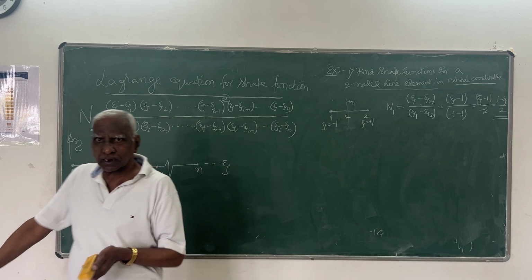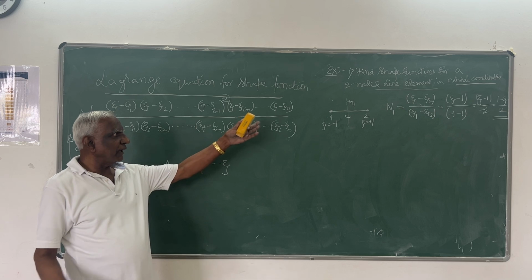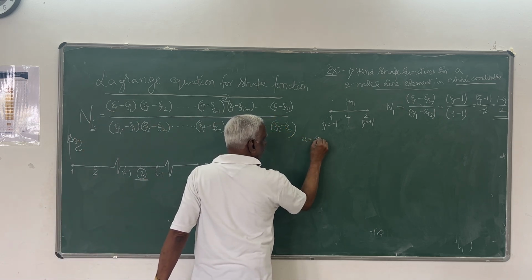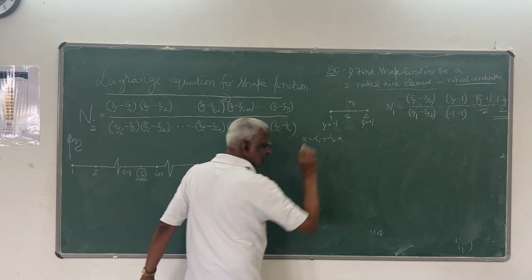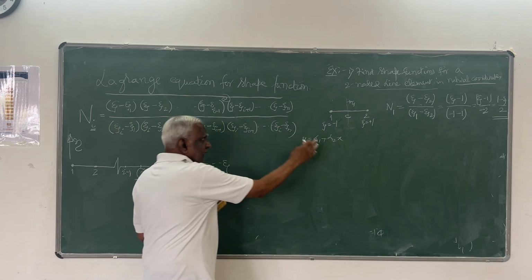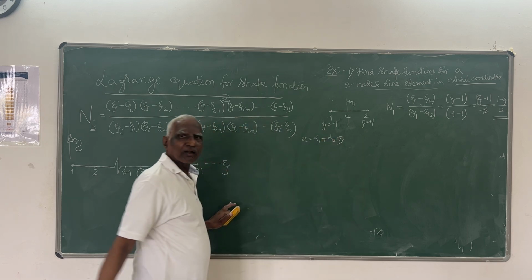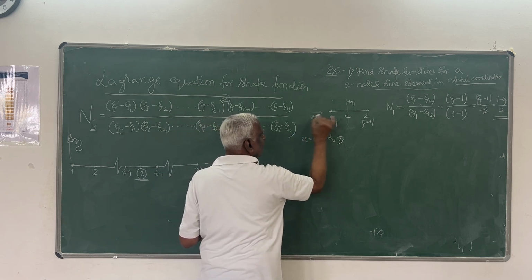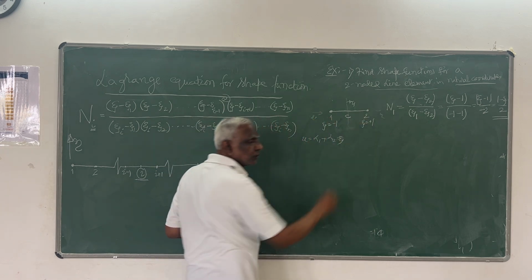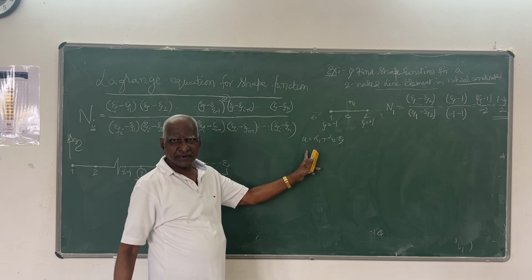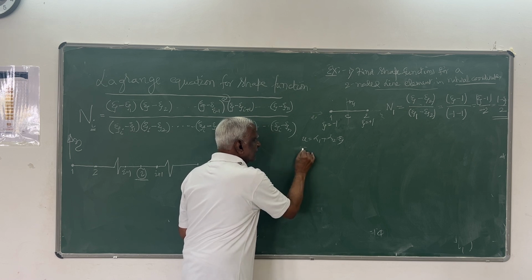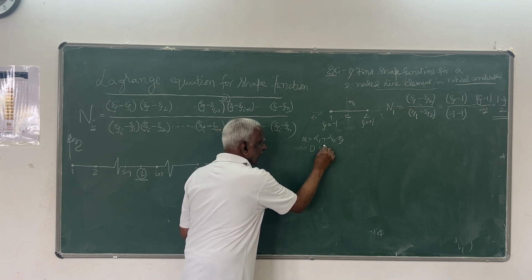Even if you adopt the general procedure, taking the polynomial as u equals alpha 1 plus alpha 2 x, in the natural coordinate system it is alpha 2 psi. Right? So here you have U1, here you have U2. U at any point is this, in the form 1 psi times alpha 1, alpha 2.